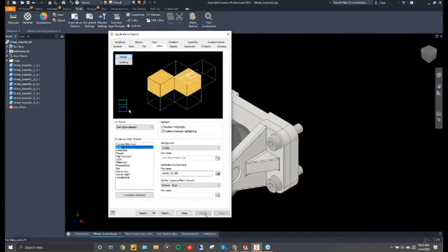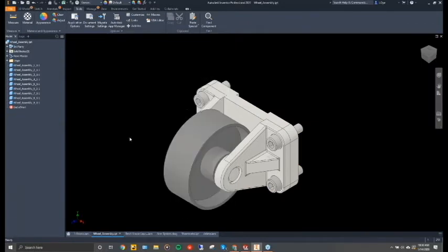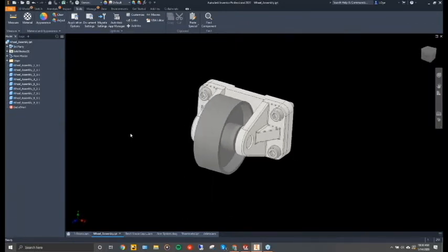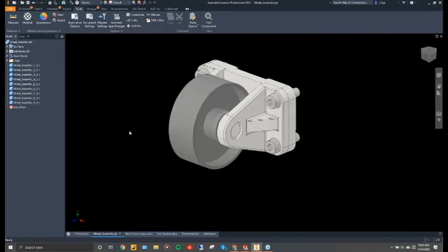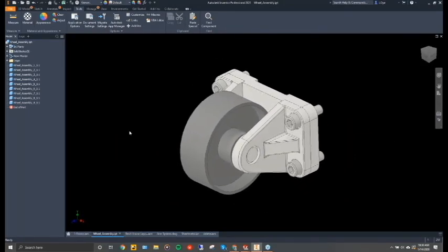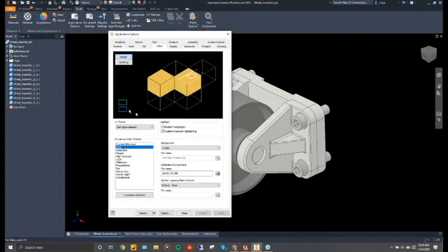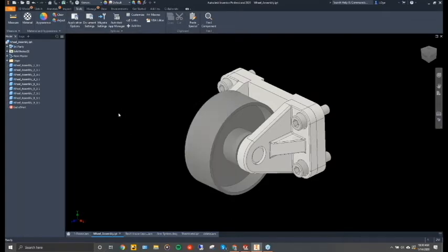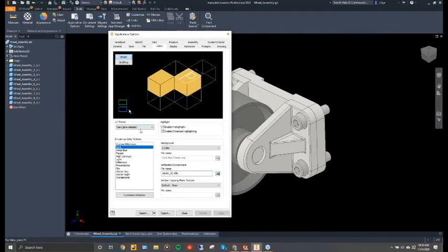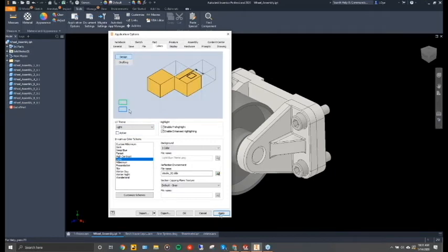So if any of you are AutoCAD lovers, I would imagine you'll love this new improvement to Inventor. And actually, when you first install Inventor 2021, this background is not going to be solid black. It's just solid black because that's the color that I selected, but it's going to be essentially an off black, similar to what you see in the model tree and the ribbon panel there. So if you don't like that, just go to Application Options. Right here, it tells you it's dark, it's pre-release. You just obviously go to light and then change it that way.